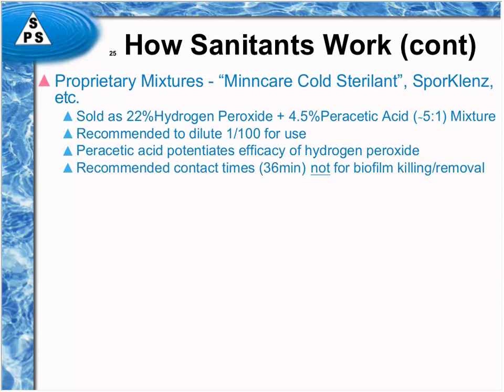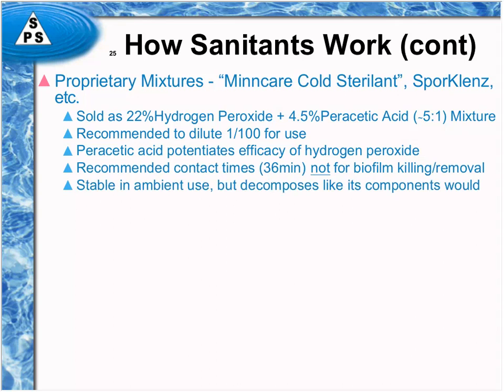And remember, when you've got those hydroxyl free radicals, they're very, very aggressive, and that's some of the beauty of its efficacy. Now, if you read the bottle, it says it works in 36 minutes. Don't believe that. That's not for sanitizing biofilms in water systems. Usually in water systems, it's used for between 1 hour and 4 hours, or even longer, depending upon how much biofilm has developed. Obviously, the shorter times if you've had very little biofilm.